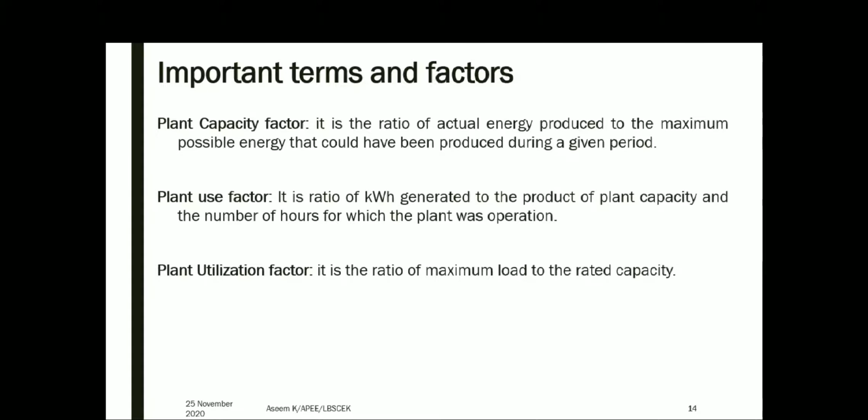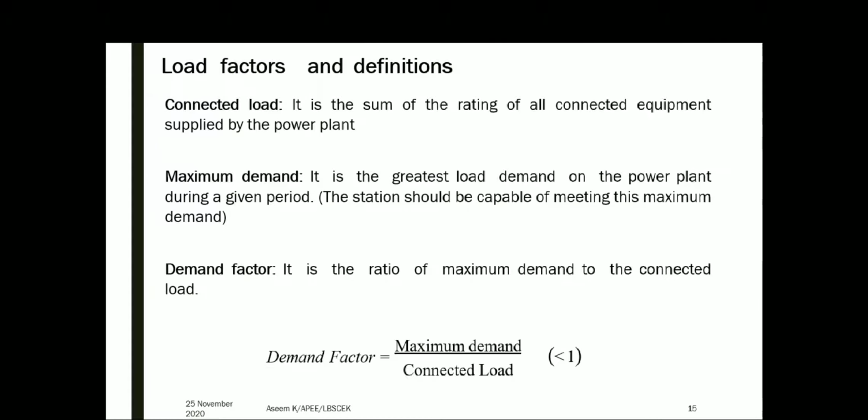Then connected load is the sum of the ratings of all loads connected to the power plant. The demand factor and maximum demand we already discussed. So demand factor, which is maximum demand to the connected load, is always less than 1.